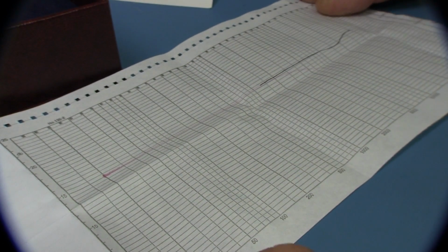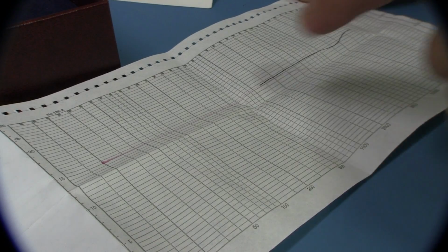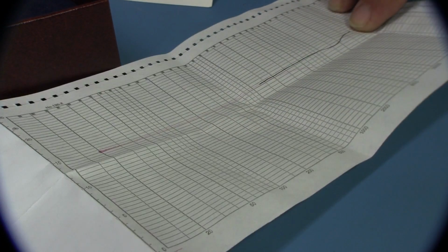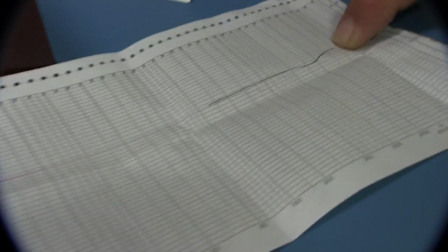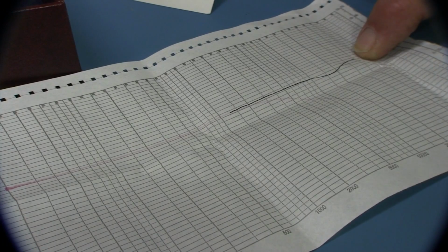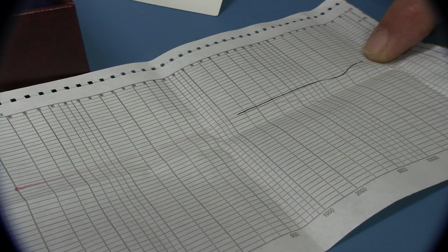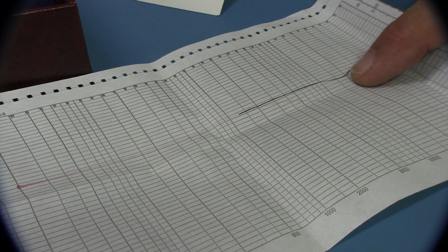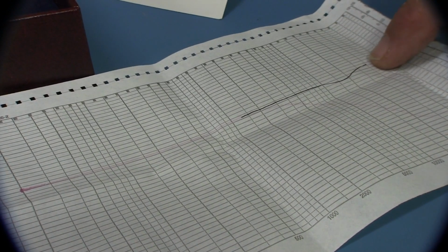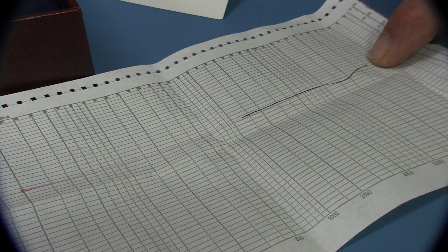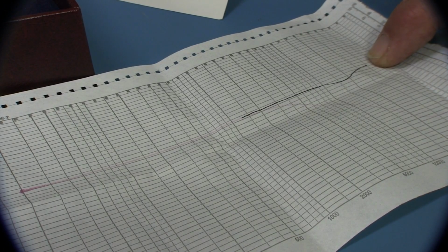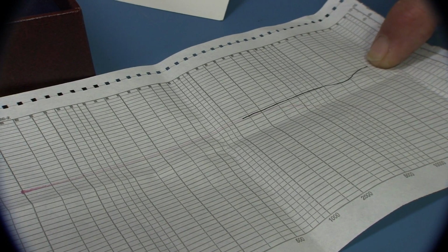Which shows the free field and pressure response, and you'll notice that that goes to 40 kilohertz. And deviates by, well, in this case, I think a dB at 18 odd kilohertz, with a positive peak of about, what's that, a dB at 40 kilohertz.